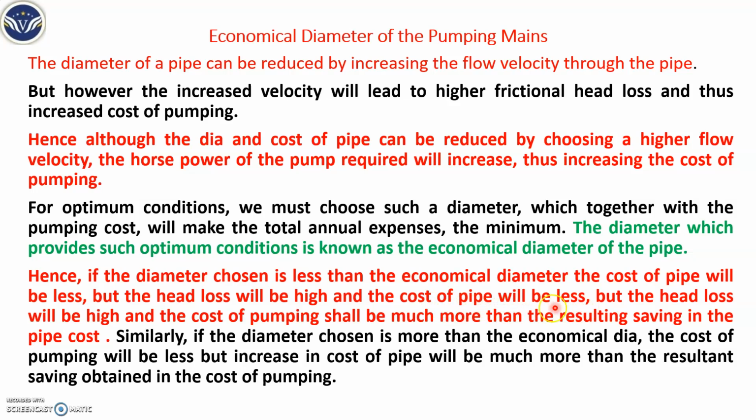Naturally the cost of pipe will be less but the head loss will be more. Due to that, the cost of pumping will be more than the resultant saving on the pipe itself, because the head loss will be more.